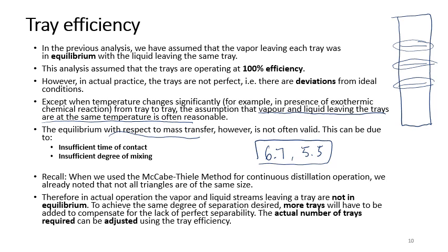We couldn't be bothered to modify these numbers into integers because these are just theoretical numbers of stages. What if it is 5.5 and the efficiency is, let's say, 0.5? Then you can actually get an integer value of, let's say, 11. So for the calculation of theoretical number of stages, we leave it at that. If it's 6.7 or 7.8, we don't have to round it up to the nearest integer.